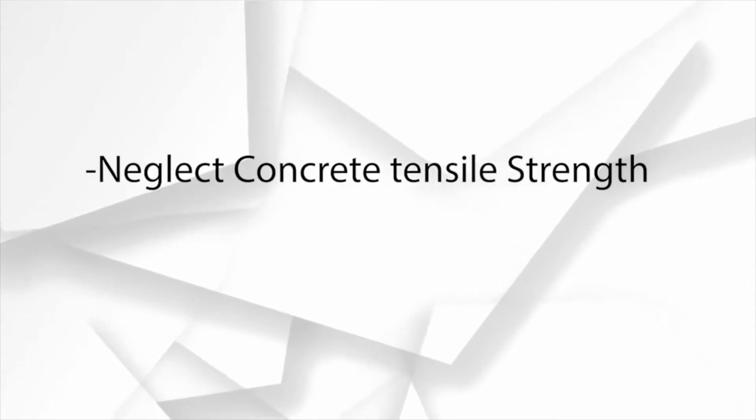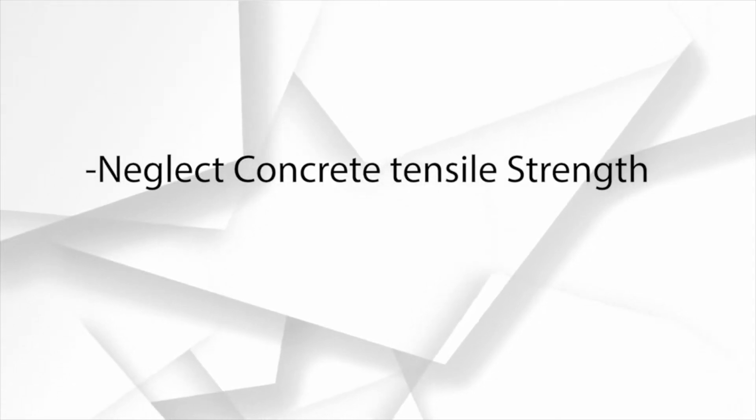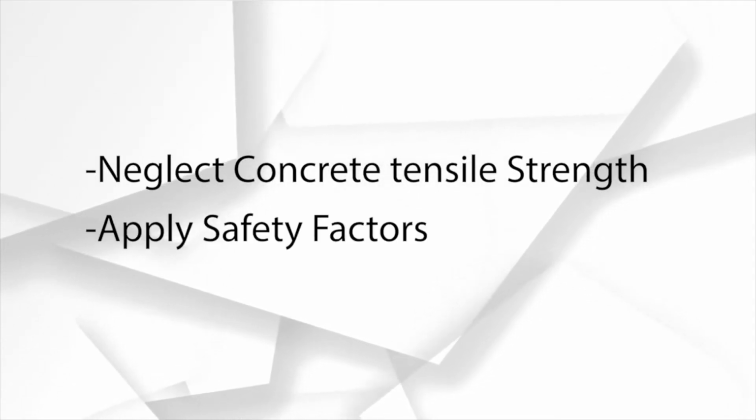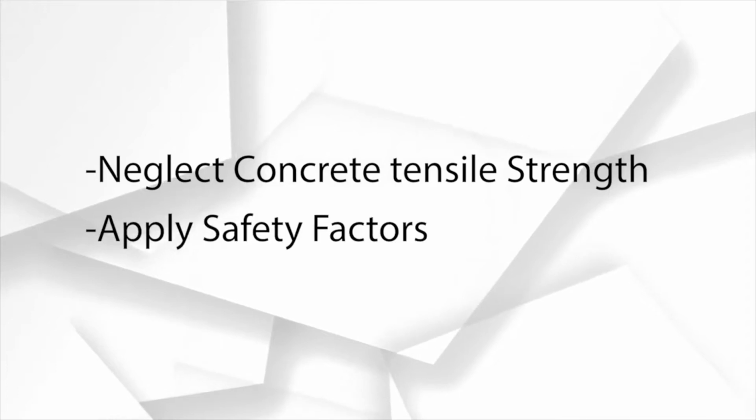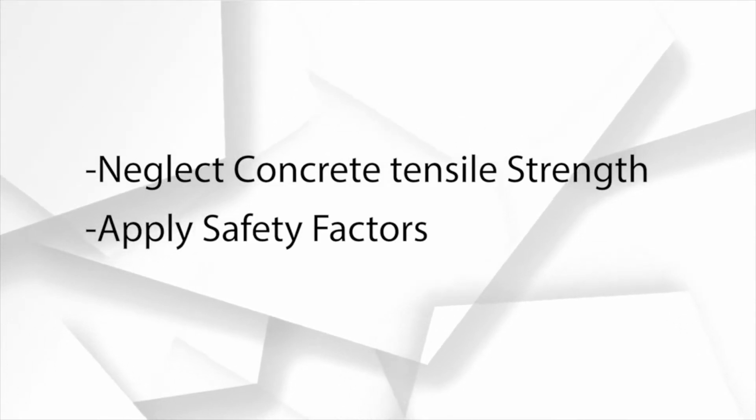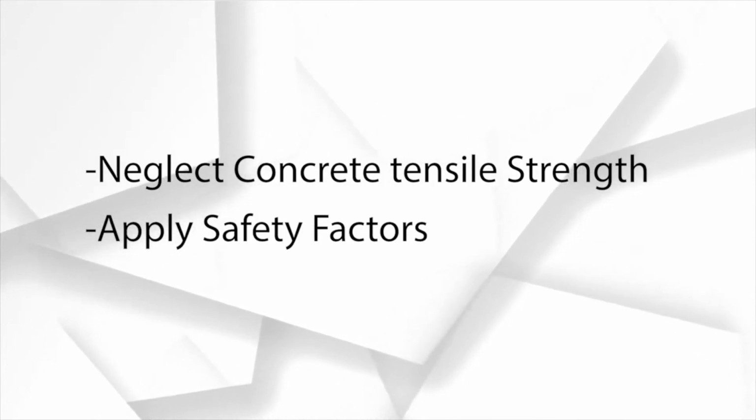Even though we said concrete has a little bit of tensile strength, we actually assume it's negligible, just to be safe and make the design process easier. We also use safety factors and load combinations in our design to make our design safer. We also want the steel to yield first.